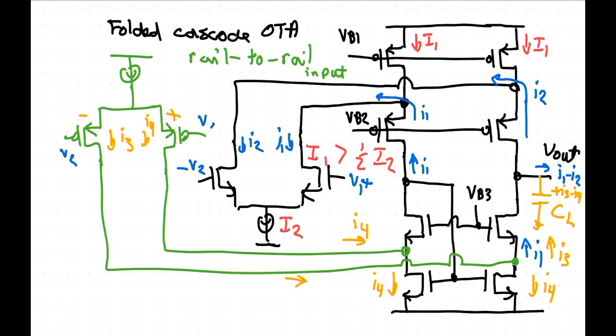So for PMOS, the source gate voltage is a threshold voltage plus an effective voltage. If the threshold voltage is minus 0.3 volt, whatever, then you probably have a source gate voltage of maybe 0.4 volt, with a 100 millivolt effective voltage. That will turn on. So you have a lower voltage there than you have there.